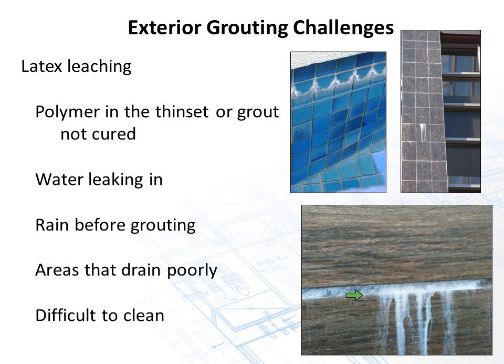And the same thing is true of this exterior commercial installation, where water got in because the parapet cap wasn't put on at the proper time. Water filled the cavity between the tile and the waterproof membrane, allowing it to come back out through the grout joint.